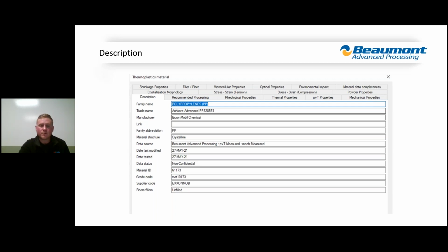There are a few key pieces of information you can get from that, which is you can understand where it was tested and how, and also when the data was tested or modified, which can be pretty important because, as you know, as the material card ages, there's a good chance that material may have changed raw material suppliers, may have changed the OEM overall. Something along that supply chain to create that material could have changed, and it may be worthwhile to have it retested or characterized to understand the behavior changes that you're going to see in the simulation and on the shop floor.